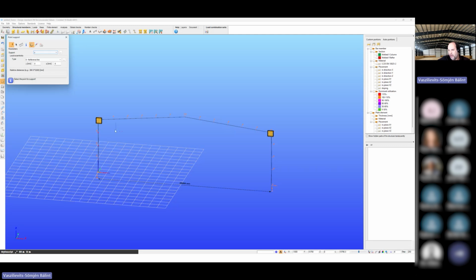Normally, in a real structure, that bracing is provided by just an angle connected to a cold-formed purlin. It will never be as efficient as a considered fully efficient, fully rigid lateral support. It will be something with a certain flexibility, and that is much closer to a spring with a questionable, unknown value than a rigid support.